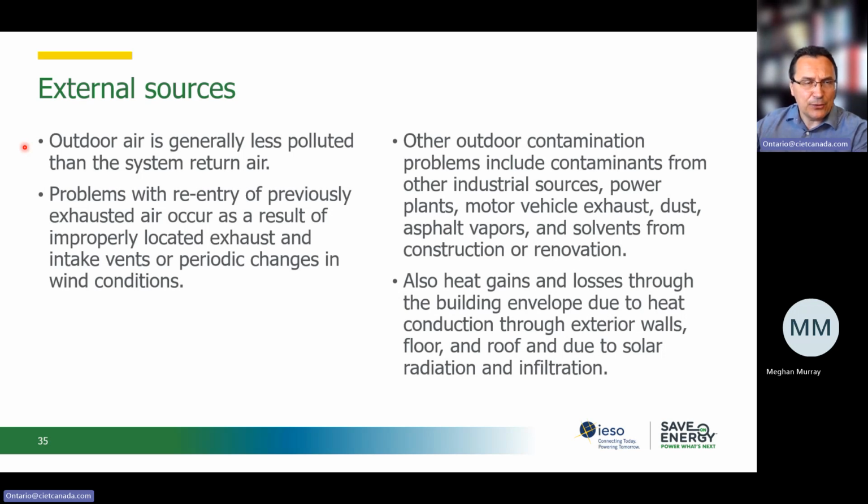But in general, we assume that outdoor air is less polluted than the air in the space that we want to dilute. So we use outdoor air for dilution. We definitely want to avoid the short circuit, the exhaust being recaptured back into the building.